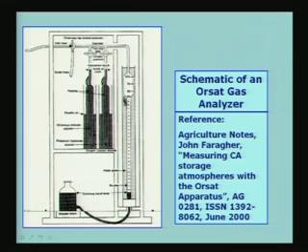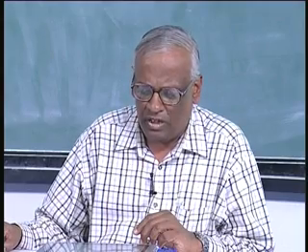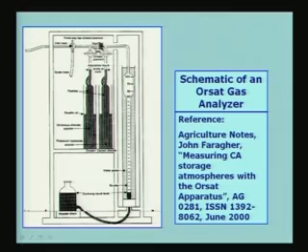So, what will happen is that the sample will be drawn into this, because as you move the liquid down, this vacant space which is created will take the sample, and the sample will fill this. Usually the sample is taken 1 or 2 times or 3 times, and then it is sent out through the outlet hose, so that we have flushed the entire burette plus the connecting tubes of the atmospheric air which should have been present to start with.